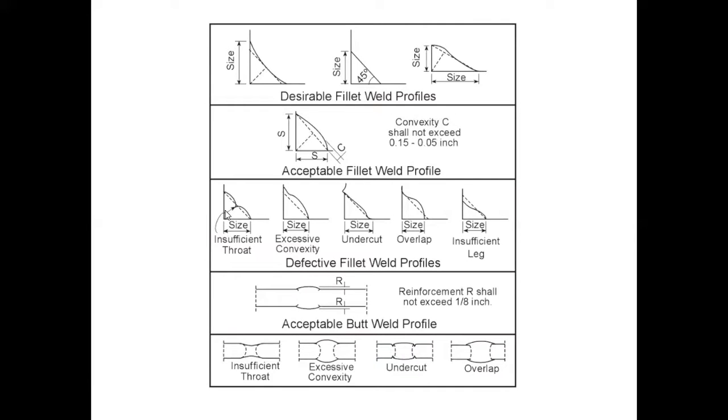But what happens is right where this arrow's pointing, we got a big valley. And as we know, we're trying to avoid those valleys in our welds. We're trying to get those caps or the ridge points of our welds to meet up nicely, have a nice flow, and pretty much be blended in almost seamlessly. This valley here protrudes below the line for the throat of the weld.